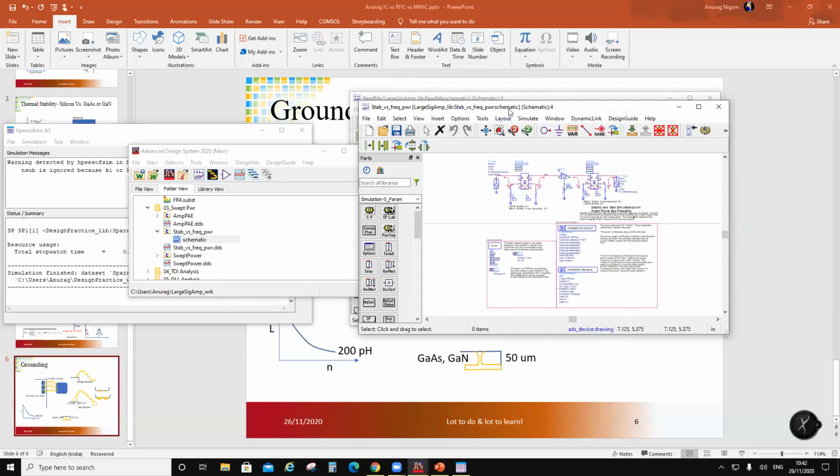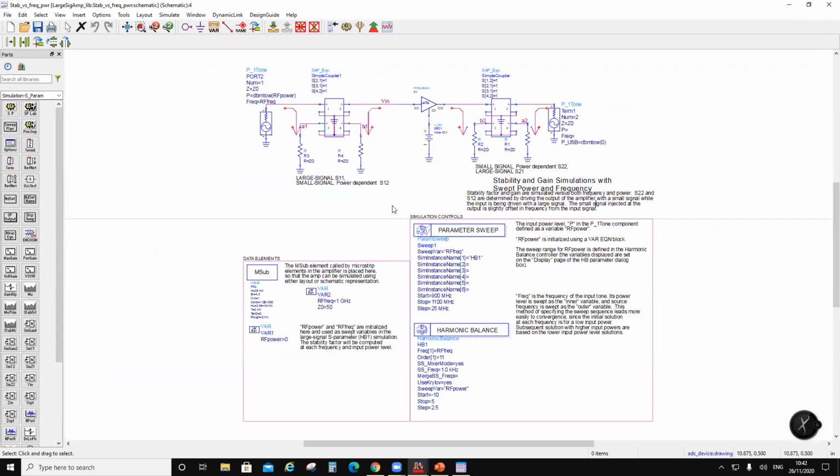Okay, so what are they doing in this workbench? In this workbench, they are putting a large signal on the input and a small signal on the output. Now, one would question, why would you put power into an amplifier from the output port? Yeah, there is no reason for putting power there. It's just for determining the output impedance.